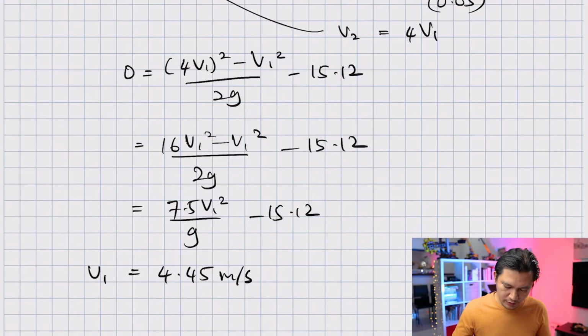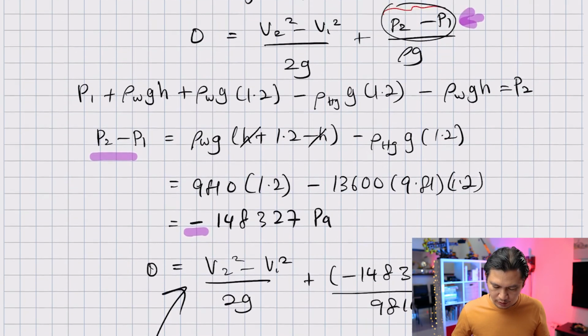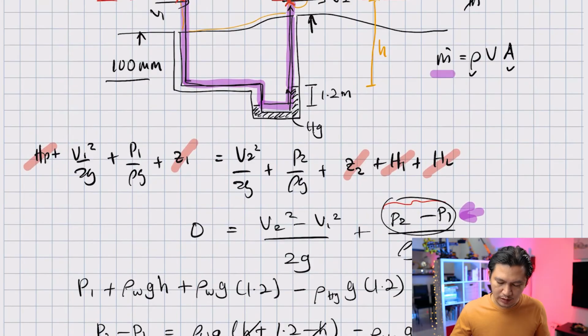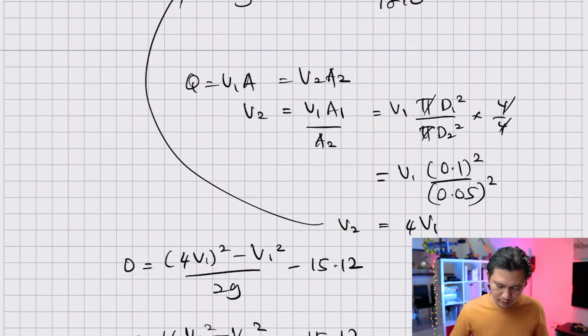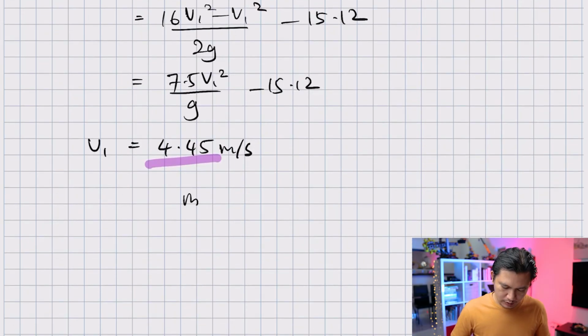And now, do we have everything that we need in order to solve the mass flow rate equation? Remember that mass flow rate is rho times velocity times area. It doesn't matter whether it's at point 1 or at point 2 because both of them will be similar. Alright, I think we're going to have it at point 1. So m dot is equal to rho 1 V1 A1.